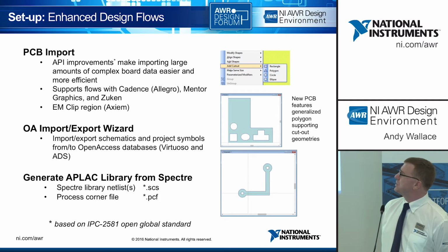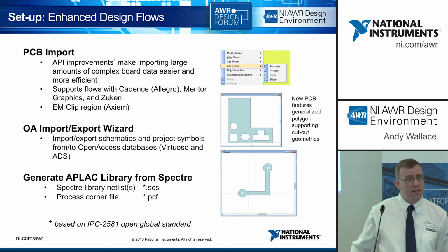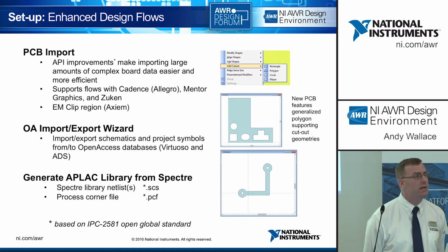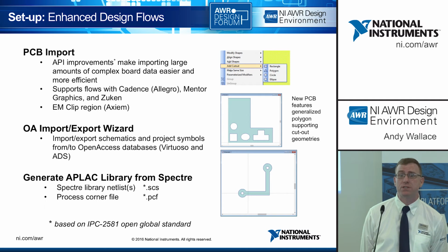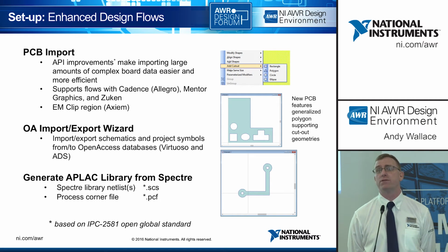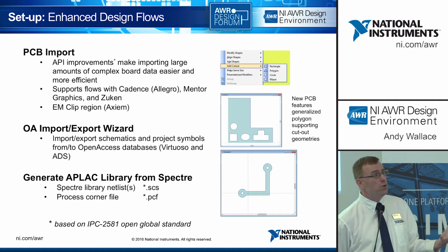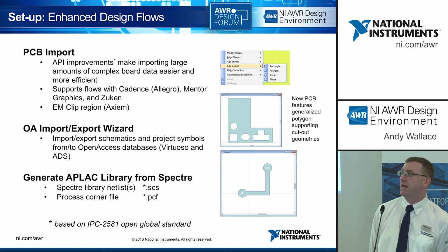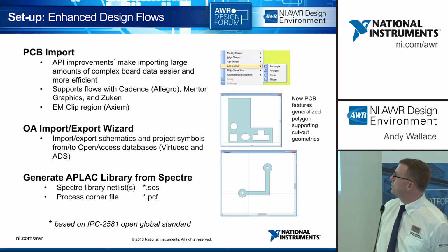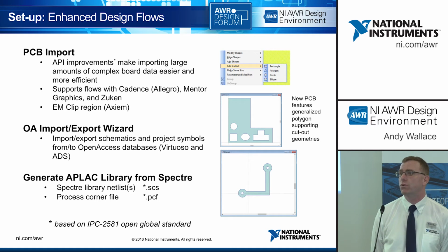One of the big things that we had to solve and resolve is the fact that the polygons that import in GDS2 world need infinitely thin cut lines to each of the internal shapes. In version 13 we don't need that any longer. What we have is the ability to draw internal shapes, modify those, move those around. So effectively a closed polygon with a cutout. Sounds like a small feature, but it makes a huge difference to the number of points on that polygon. And it doesn't start from A to B and end up back at A. It can have cutouts all the way through. And again, the small trace down on the bottom right-hand side, and we can add those cutouts as rectangles or imported shapes.